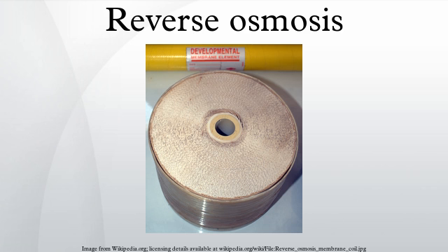Prefiltration antiscalants. Scale inhibitors prevent formation of all scales compared to acid, which can only prevent formation of calcium carbonate and calcium phosphate scales. In addition to inhibiting carbonate and phosphate scales, antiscalants inhibit sulfate and fluoride scales and disperse colloids and metal oxides. Despite claims that antiscalants can inhibit silica formation, no concrete evidence proves that silica polymerization can be inhibited by antiscalants. Antiscalants can control acid-soluble scales at a fraction of the dosage required to control the same scale using sulfuric acid.